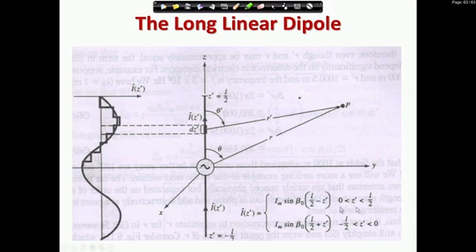So, that is why we need to break it into the two poles. Here it is L/2 minus z dash, here it is L/2 plus z dash. If you do that, then you see what is the thing at the center: at the center, z dash is equal to 0. So, this thing will be maximum here, depending on the length of the antenna. It has some non-zero value here, but at the end, z dash is equal to L by 2, so sin 0 will be 0.